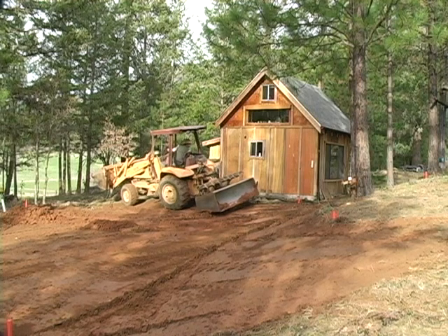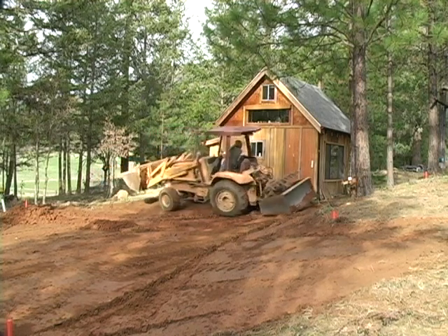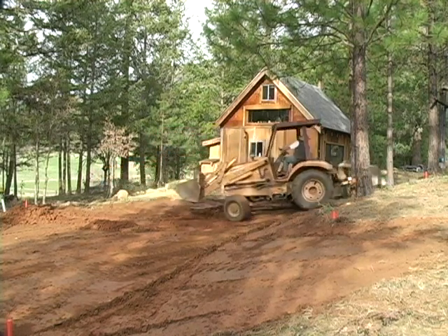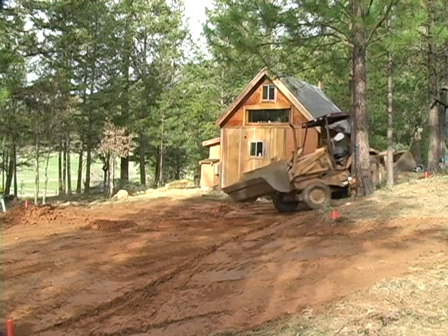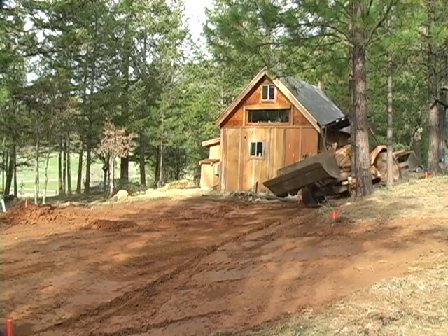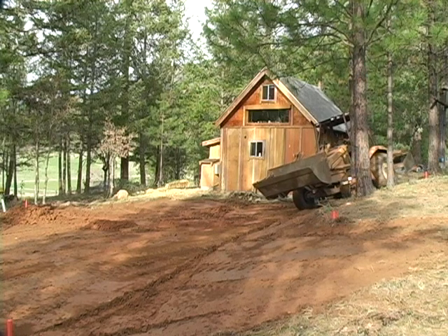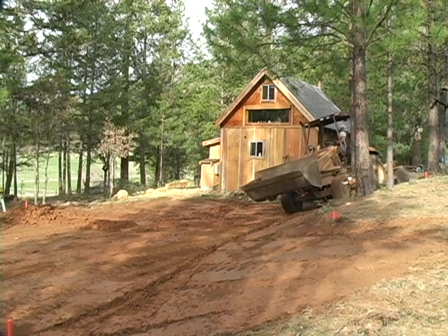Now we're going to actually cut this down a little bit lower than we need to go and build some areas back up with some compacted stone. So the excavator is aware of that, and we'll have to check our grades as we go along here and make sure that we're staying within our tolerances for what our final goal is.